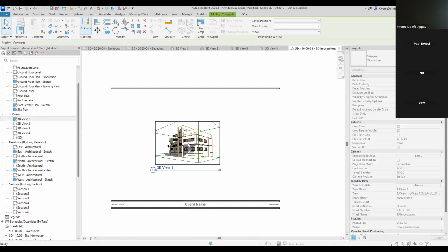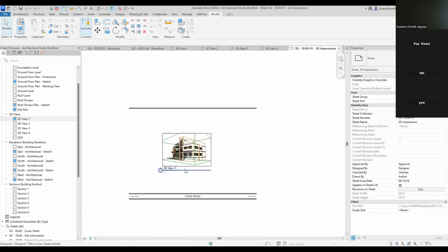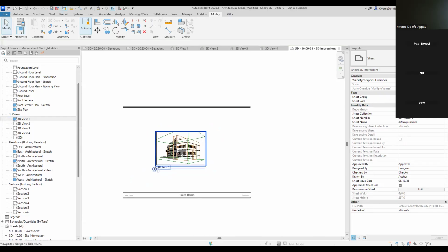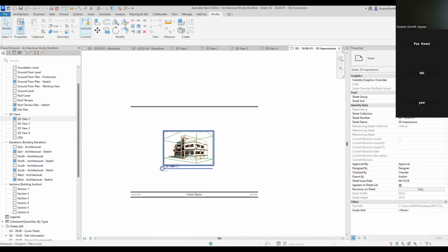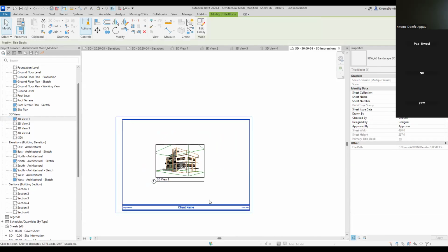On the sheet. So this is it. When I put this 3D view on this sheet, I want to put 1 view per sheet. But if I put the view on the sheet, you realize that it is too small compared to the sheet. And I know that this A3 sheet from the side here to the side here is 297. From the side here to the side here is 420. So my view size should be something close to 297 or 420.